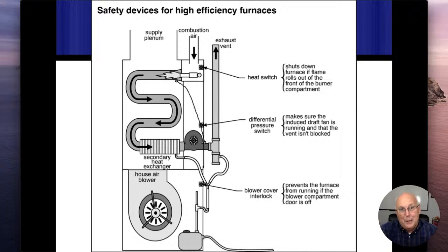I want to let them know the argument of the person who put it on there, because sometimes the doors aren't sitting tight, and the furnace will shut down and you're not going to know why. You're going to call the heating person and be upset that there's a $150 or $250 service call just because the door was loose and you didn't recognize that.